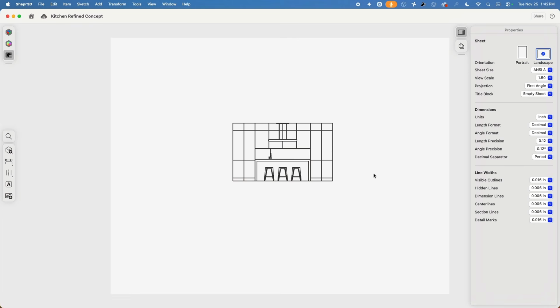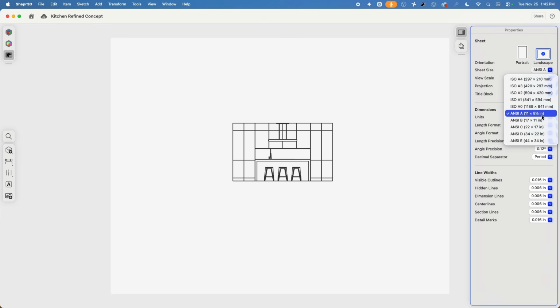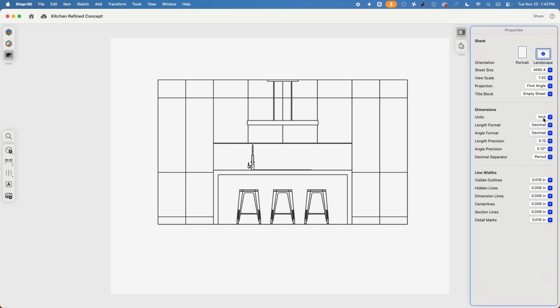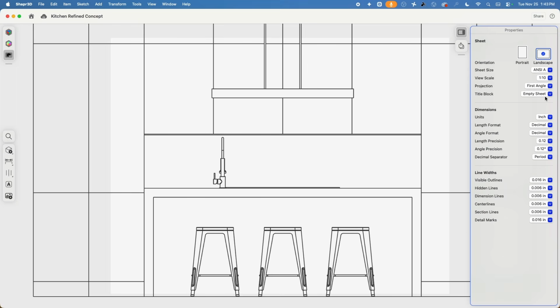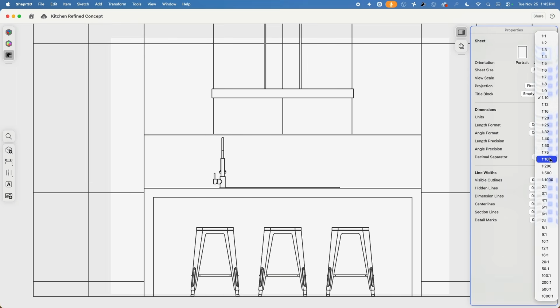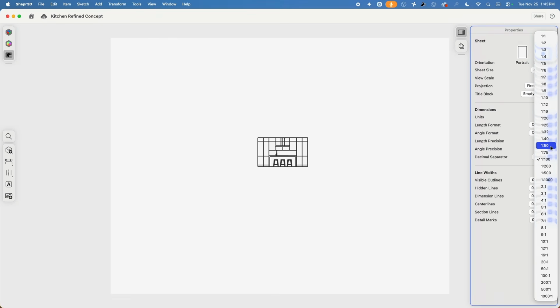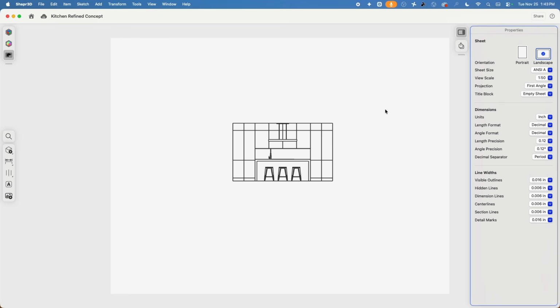presentation document. And our presentation uses 8.5 by 11. Also, this is using 8.5 by 11. And the scale factor or view factor is going to be really very important because if I set this to 120, I only can get one of such a drawing on a sheet, but I need to have multiple views. So based on how many views I need, I might have to consider the scale factor. And if I'm going too small, these drawings might be difficult, for example, to read. So I found 150 works out really good.